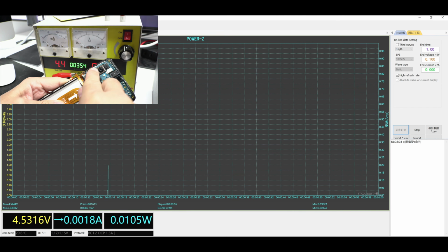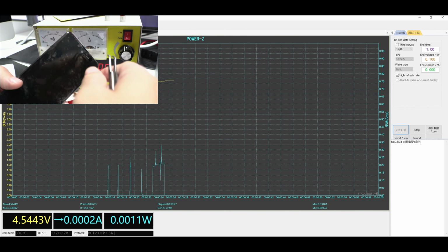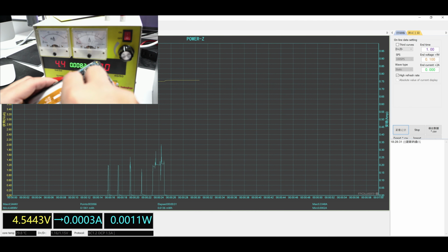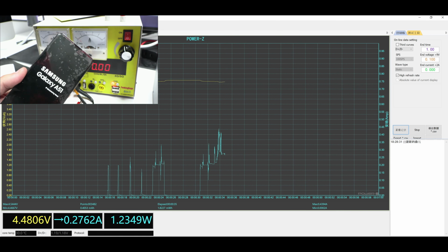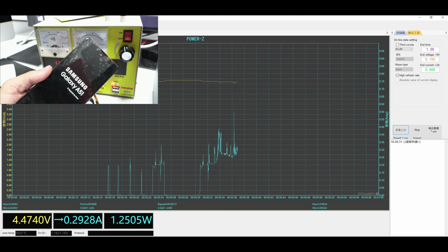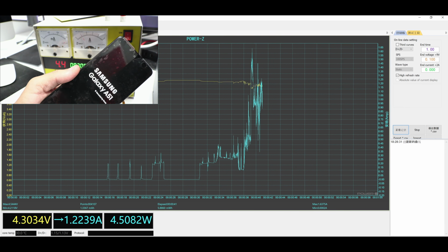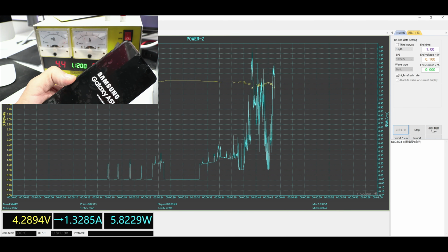Let's see this Samsung A51. We check the power button 3 or 4 times for half a second and we observe a slightly high current reaching 200 milliamperes. First, we must inspect the PMIC inputs and outputs. Then, we continue with the complete power-up cycle to see what happens. We observe peak currents of up to 1.5 amperes and then the current starts to decrease gradually.